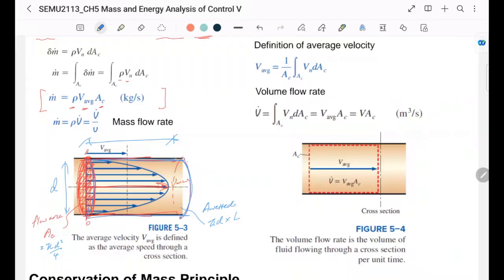It's an area wetted by the flow. Not too much of your concern here, but this cross-section area is important when we analyze heat transfer, because this is the area that comes in contact with the surface, with the flow. So here we're only dealing with the flow area, but just to let you know that there is actually another area called the wetted area. For the flow rate, we'll be looking at the cross-section area that's perpendicular to the flow.